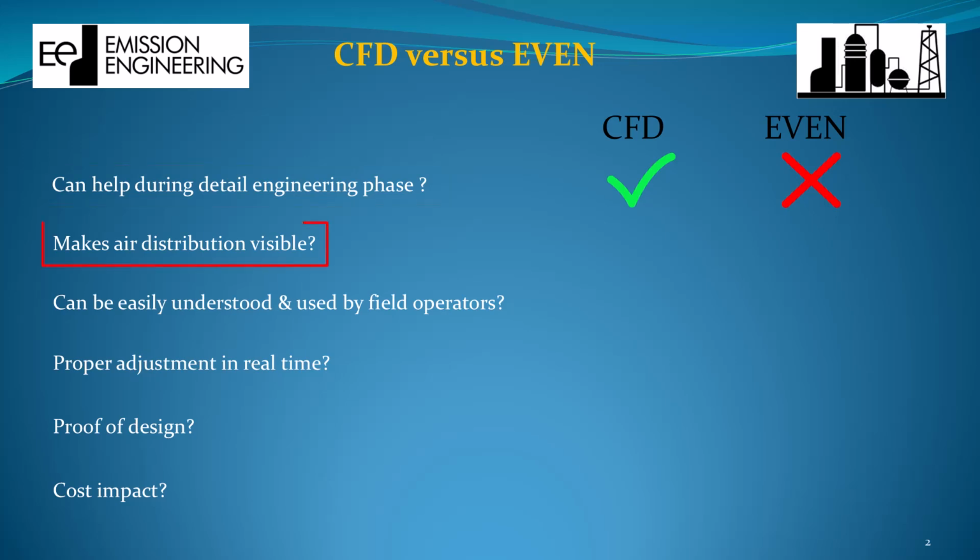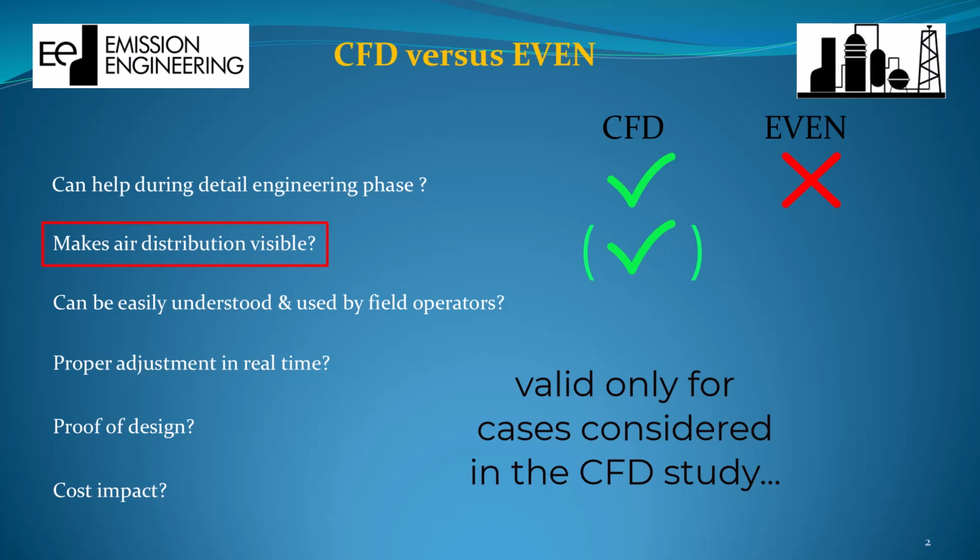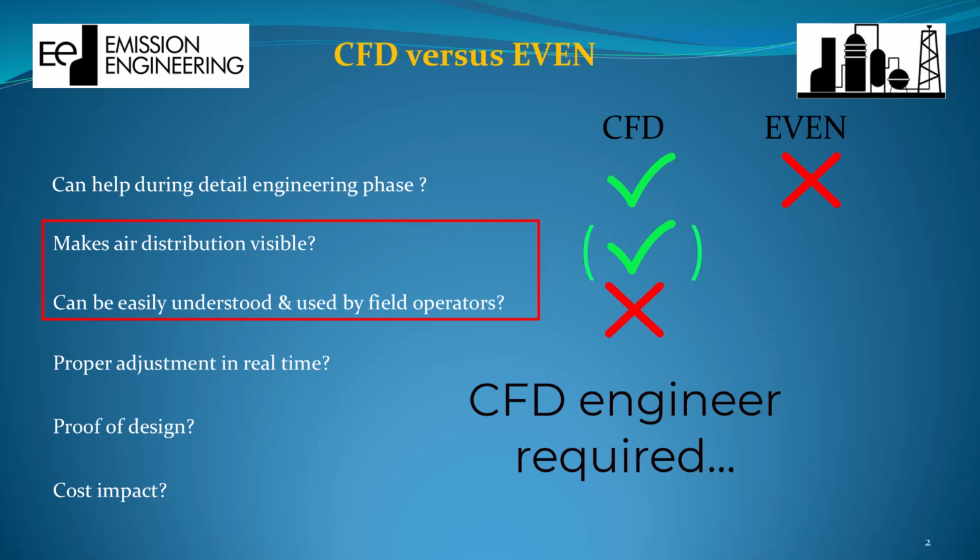The results of a CFD analysis are usually presented in the form of beautiful, colorful images, which usually seem to be great scientific proof for the client that the design was carried out correctly. The problem is that these only apply to the calculated operating cases at best and not necessarily to every real case. In addition, the accuracy can only be verified with detailed specialist knowledge of CFD modeling. As a rule, this does not apply to normal plant engineers and certainly not to plant operators.